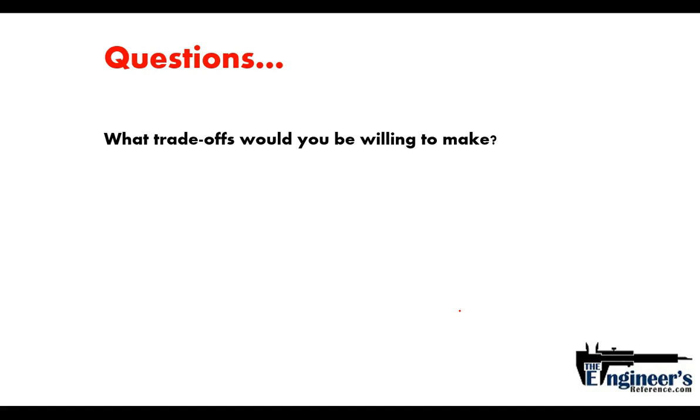What burden of manufacturing are you trying to preserve or take away? Does the expected volume justify your overhead? What type of overhead are you going to expect if you introduce a new process, where you say, well, I'm going to eliminate this machining process or this grinding process? Will your volume, the number of parts you're going to make, pay for itself?